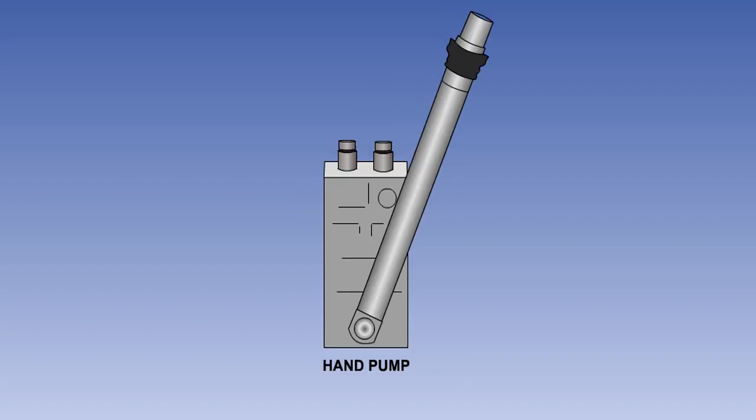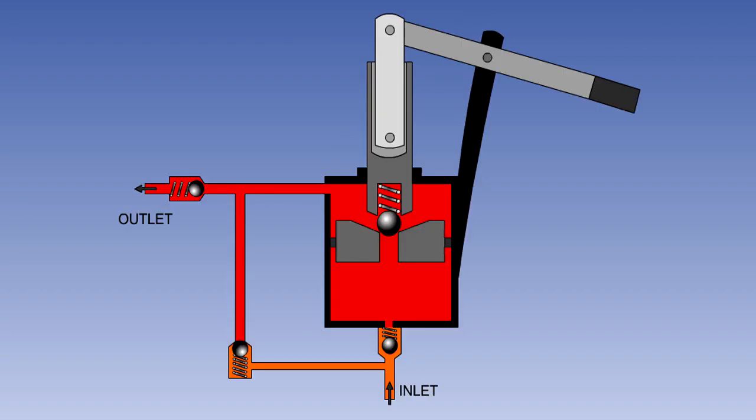A hand pump may be the only source of hydraulic power in a light aircraft hydraulic system, but in larger aircraft, hand pumps may be employed to allow ground servicing to take place without the need for engine running, enabling lines and joints to be pressure tested and cargo doors to be operated. The hand pump is usually a double-acting pump, delivering oil on both strokes in a very compact body. It incorporates non-return valves and a relief valve, which can be set to relieve at any required pressure. Typically, this is about 10% above normal system pressure.